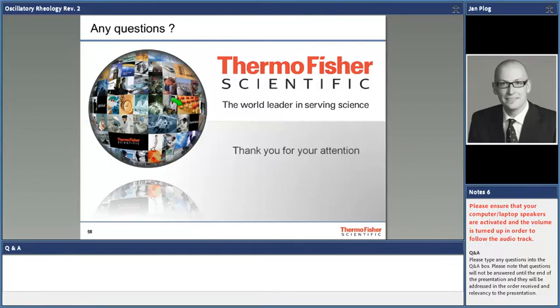Another question from Carlos: if G prime and G double prime can cross again after the elastic regime? Usually not. I mean, this behavior I was showing you, the speed-dependent behavior after the elastic plateau, when you further increase the speed, you will go into this dynamic glass transition. However, in that glass transition, also your elastic component will always overcompensate the G double prime.